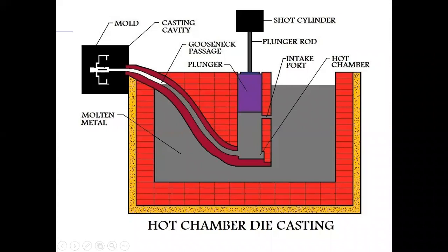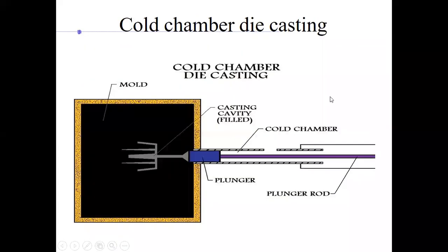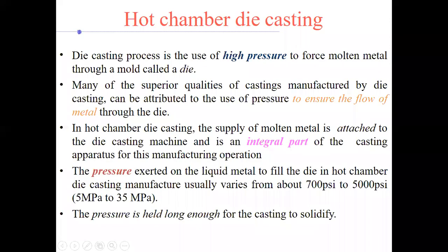So this is basically the temperature that you are trying to achieve and the time that is required, because if that molten metal was melted at some other place, while traveling it would have had some oxidation or slag and a reduction of temperature. So all that can be avoided when you have hot chamber die casting.